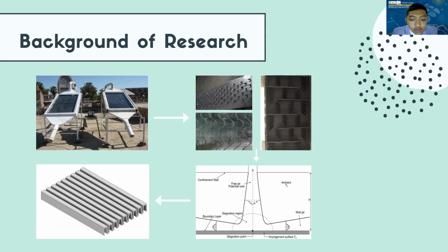Jet impingement provides holes or gaps, and jet impingement is a heat transfer method in which the fluid is emitted through holes or nozzles to a surface or plate that has a temperature difference. Impinging here means collision, which is a collision between the coolant and the surface of a target at high flow rates. This method can also be used to heat a component or a certain material, like a food drying process.